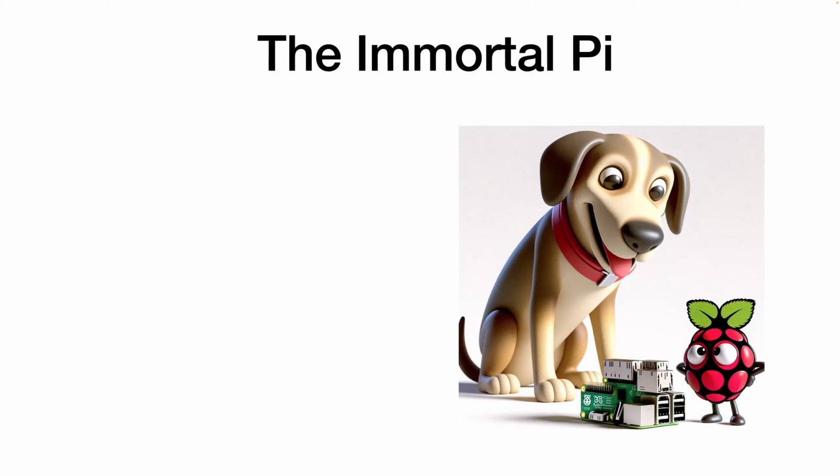And we found a way to get out of that dreaded frozen Pi situation. It's a little known feature. It's built in every Pi, and it's a hardware watchdog. And the hardware watchdog is great because it has the ability to restart the Pi even if the entire OS is frozen. It can do its magic because it's in hardware, so it's always there running even if the OS is frozen. There are pre-made packages that you can install to control it. But if you're like me, you say, hey, I can do better than the rest of the universe, right? So you want to build your own stuff, which we did. And it turned out to be fairly simple.